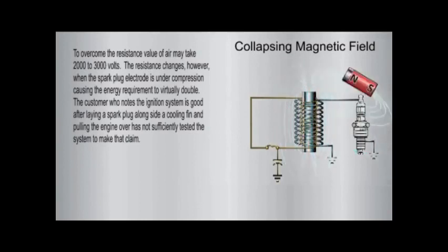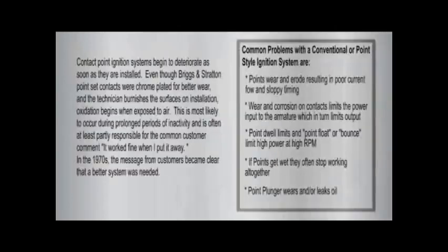The customer who pronounces an ignition system as good after laying a spark plug alongside a cooling fin and pulling the engine over has not sufficiently tested the system to make that claim.